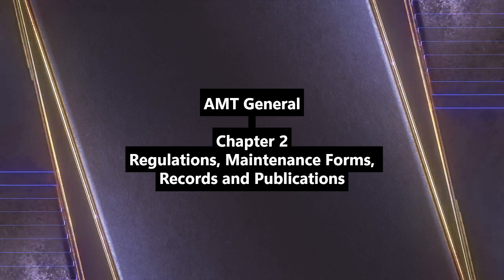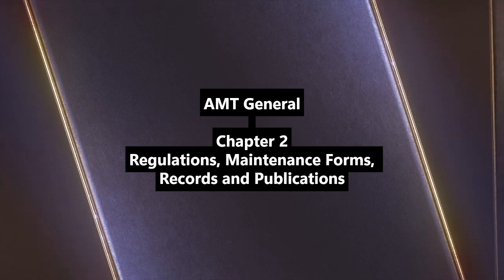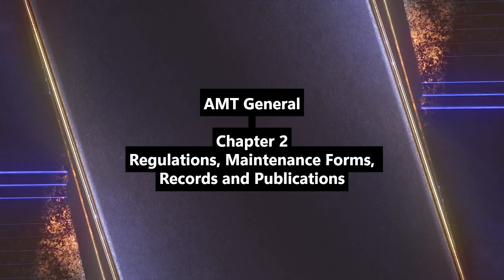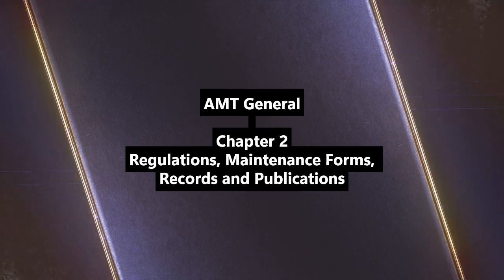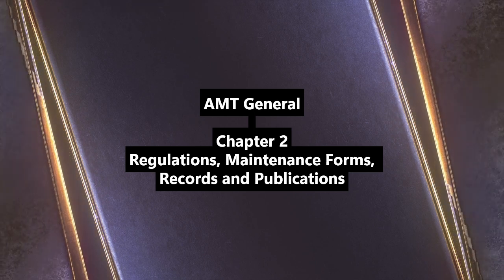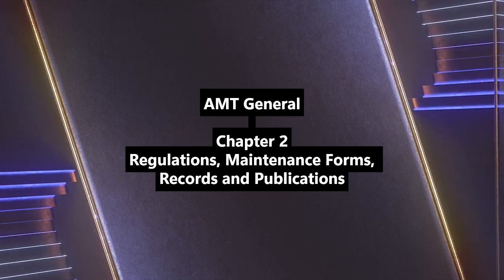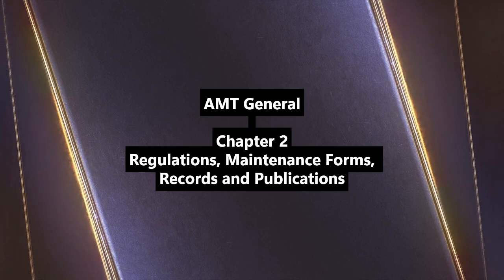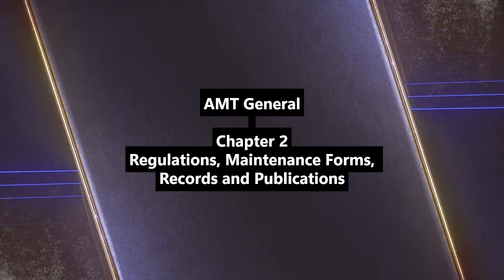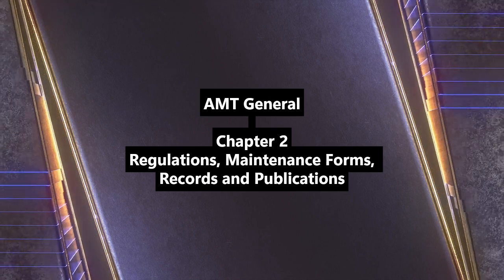And what about for modifications, like an STC? If the STC was developed after 1981, it must come with its own complete set of ICAs, too. So the mechanic knows how to maintain the modified parts. Precisely. And these ICAs have to cover 16 specific subjects laid out in the regs. They're really detailed. Okay, vital stuff. Now, what about the standards the aircraft itself has to meet?